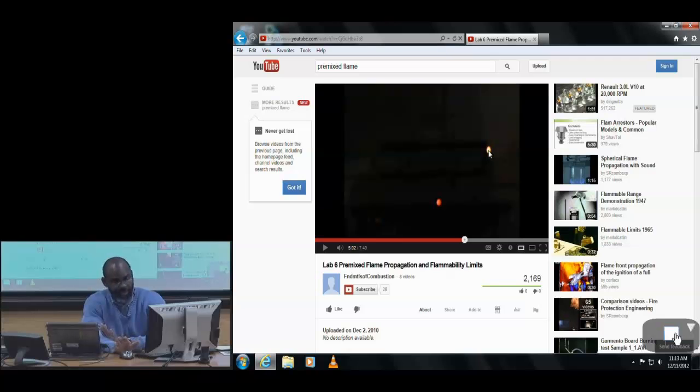Why was the diffusion flame bright orange? Because the solid particles, the soot particles in the flame, were radiating broadband and allowed us to see this orange glow. Here he has an igniter, and you're seeing that igniter as orange, which is because it's a solid. And when he ignites this mixture, you're going to see this mixture as blue, and that blue is